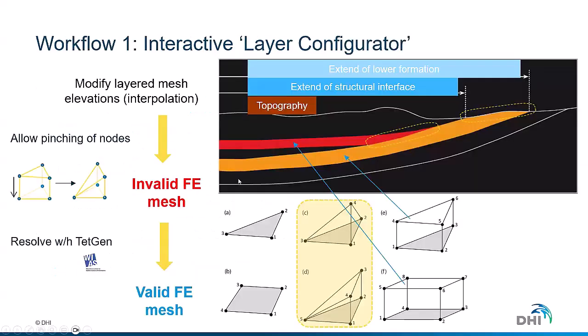In any case, I would like to give you a very quick overview of all the other workflows. Workflow number one basically means that you have elevation data, so you have point data, not surfaces. You pass this point data into FEFLOW, and following certain rules, FEFLOW will construct the different slices, and the slices will define layers. After you are done with this workflow, FEFLOW will give you the possibility to create still continuous layers, so prismatic elements, or to decide if there is an intersection.